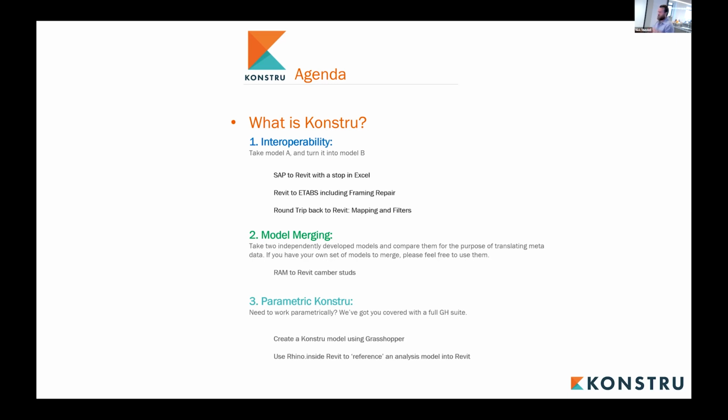And the key feature we're going to discuss here is the ability to repair the connectivity of the framing of the model. Whenever you move from Revit into an analysis platform, because Konstru will literally read the XYZ start and end coordinates of the objects, if those end coordinates are in a bad position in terms of things not connecting together, then you're going to have issues you have to resolve in the analysis model. So the goal is Konstru now includes a set of tools that should be able to very quickly repair any issues you have with the model before you translate.